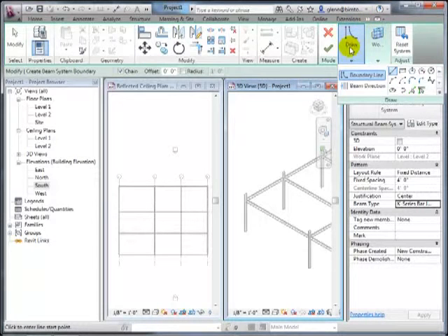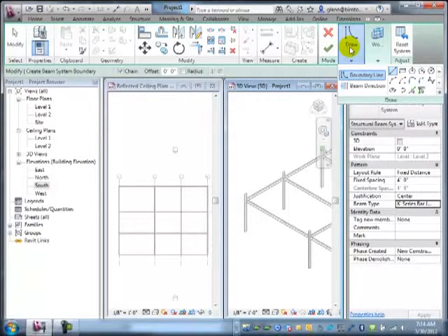What I'm going to do is basically draw a boundary. And this is kind of a common thing. We're going to do this with floors, with roofs, with anything. There are some elements, like the columns, that we were able to put in as individual sticks, individual pieces of the beams. We said it went from here to here, drew a line and put it there. But there's a way you can do it by touching those side beams. Oh, exactly. We're going to do that. Yes, exactly. It's easier than drawing. So we have to say what the boundary is. And we could draw the boundary, and again, drawing is okay, but we never like drawing because drawing is not as powerful as picking. If you pick, then it'll be understood that it's going to rest right on that beam.